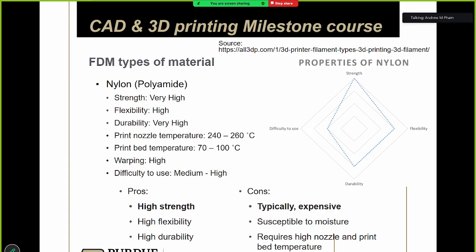And a lot of the time when you're printing engineering materials, you're looking for added rigidity anyways. So a lot of people will print something like CF nylon, right? Or it'll be labeled as PA6 or something like that. There's a lot of different nylons out there. There's different amounts of carbon fiber in the nylon, depending on what kind of nylon you buy. It can get a little complicated, but you can get very different mechanical properties out of it.